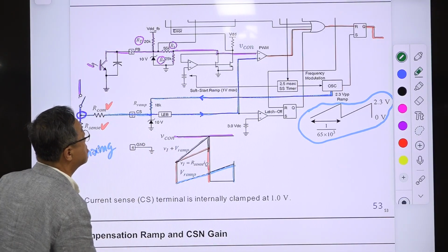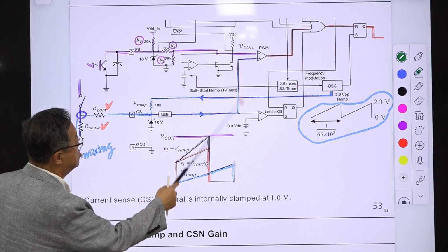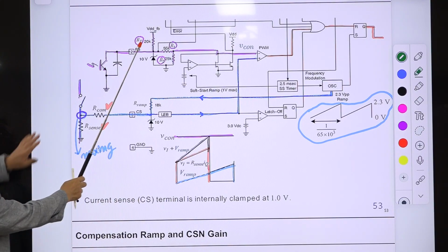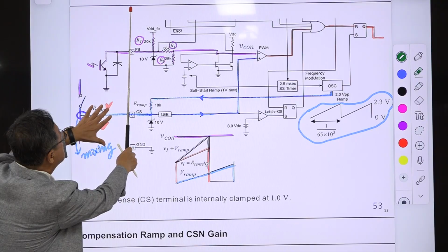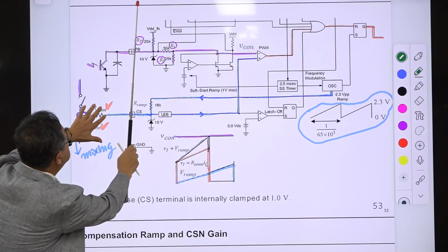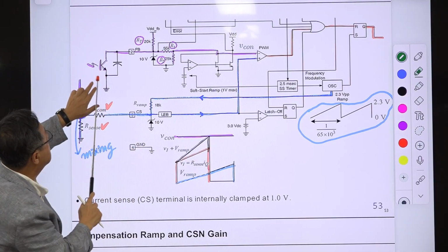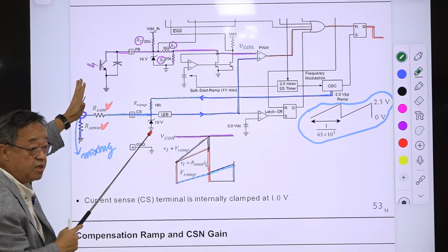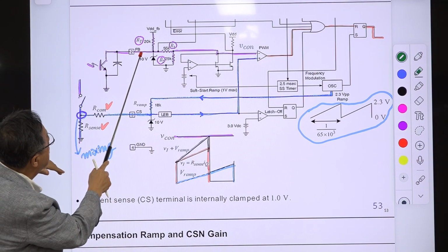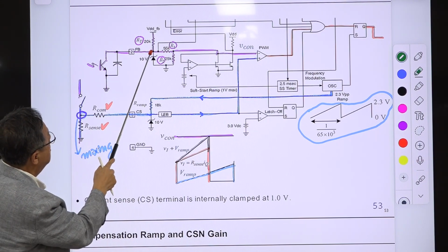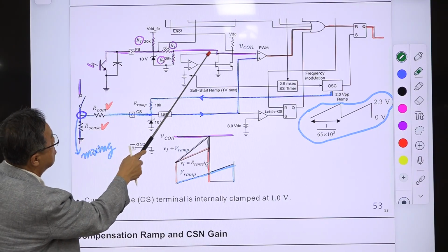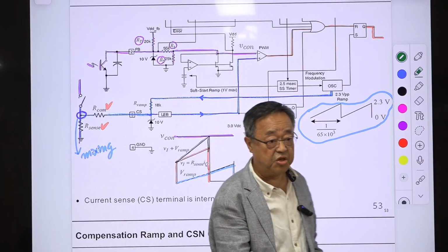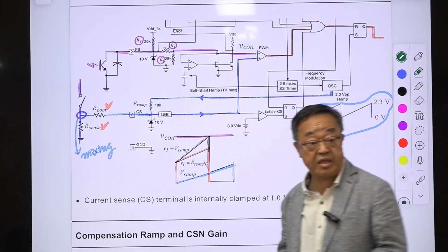All right, and this is the soft start, some protection, something like that, and this is out of this one. Okay, so borderline of this NCP something is here. So this is this optocoupler photo transistor side. Okay, then this feedback signal is some voltage division, and the part of that is going through this, and compared with this, then this gate drive signal is generated. Okay, that goes in the gate, right?